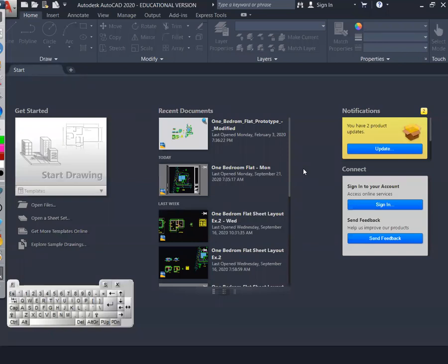Now the draftsman has to go and review the drawing file to update it based on the comments made by the reviewer. So what the draftsman will now do is go to AutoCAD. Remember, it's not a DWG file that was reviewed. The file that was reviewed was a DWFX file. So the draftsman will have to go to the View tab in the software.